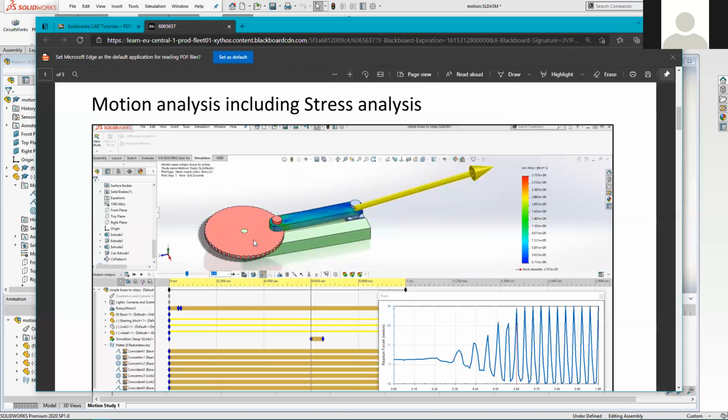So our little machine that's got this spinning plate. The spinning plate, we impart some motion into the plate. So we imagine that in SolidWorks terms, it adds a motor to the plate, so the motor can accelerate and decelerate and keep spinning at whatever speed we specify. And then that plate obviously will drag that link around its perimeter. And as it drags the link, it will cause that bearing block to slide backwards and forwards.